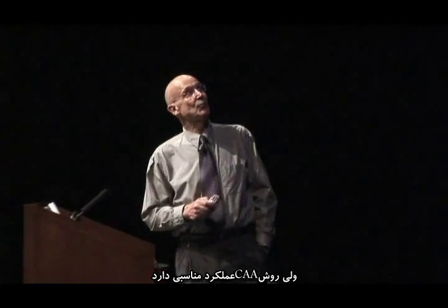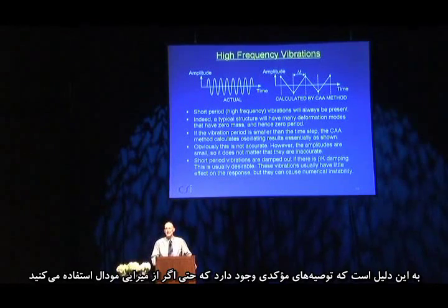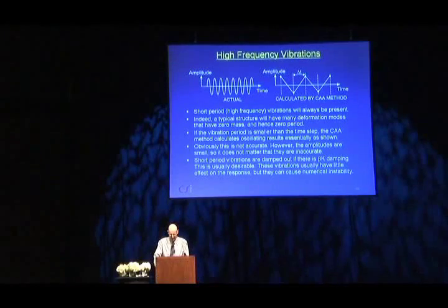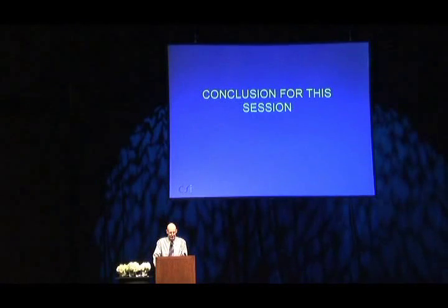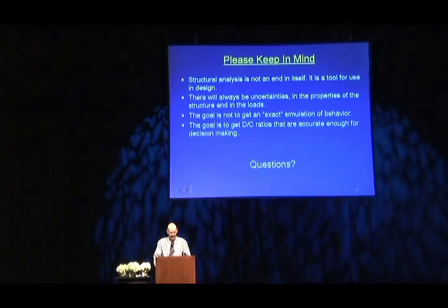But the method works fairly well, but on the other hand, it's not a good idea to have these things floating around. And this is one of the reasons why I strongly recommend that even if you use modal damping, you put in a small amount of beta K damping. And then for these very high frequency components, even a small amount of beta K damping will get rid of these things, and they'll be so small they won't create a problem, and it won't really alter the response very much. So let's conclude this session.